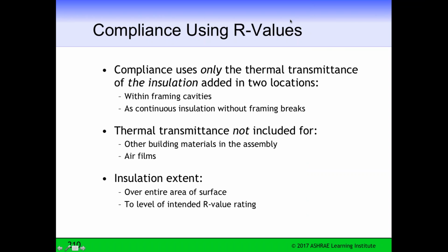Now, as I said before, if you're complying, you can comply using the R values. In this compliance, you're using only the thermal transmittance of the insulation layers within 2 locations, the insulation within the framing cavities or as continuous insulation without the framing breaks.